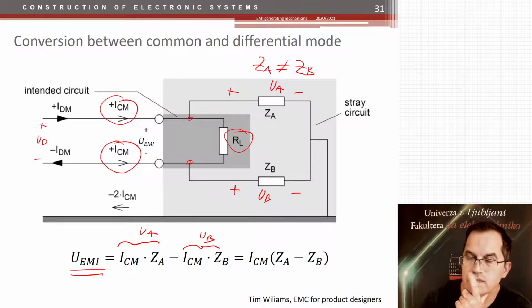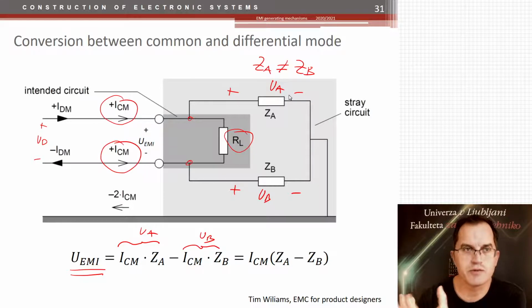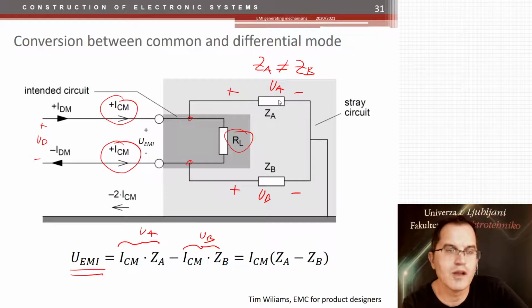So you can keep these two impedances similar, but you don't always have the means to do that, because these can be unintentional impedances. Some impedances that are formed by the surroundings in the circuit due to the geometry, not due to the actual component that you put there. Because you might not put anything, but there would be there as stray capacitances and stray inductances.